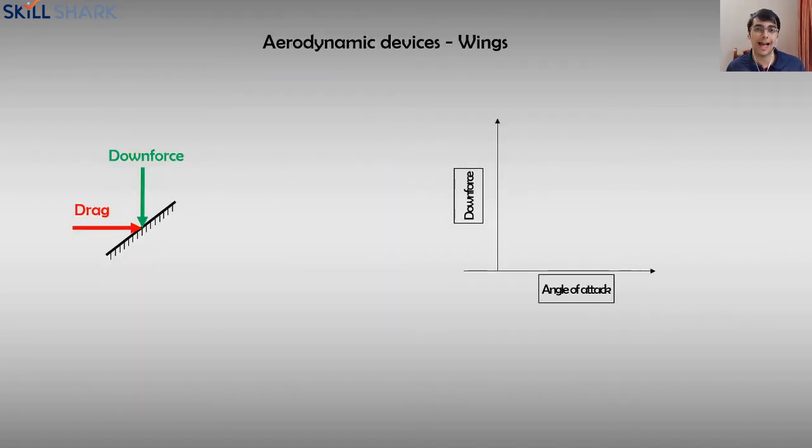We have something called the angle of attack. So that's basically the angle made by the object that you're looking at the moment with respect to the flow. So as you increase the angle of attack, you basically angle that object more aggressively with respect to the flow. So in this case, of course, if you increase the angle, it's going to rotate counterclockwise, the plate, assuming the plate is moving towards the left or the air with respect to the plate is moving towards the right.